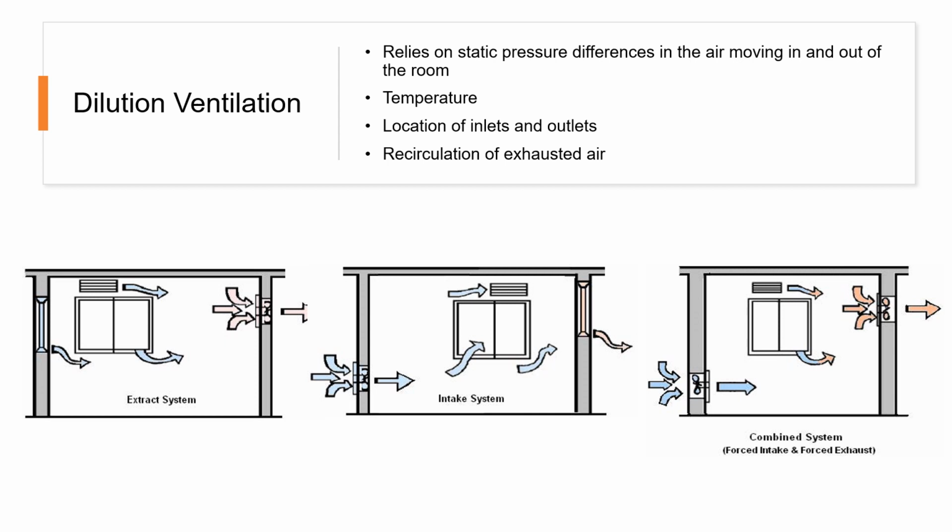So this results, the fan pushing the clean air in results in a lowering of the neutral pressure level, or the level in the building where the interior and exterior pressure levels are equal. This lower neutral pressure level then drives the air out the passive outlet.